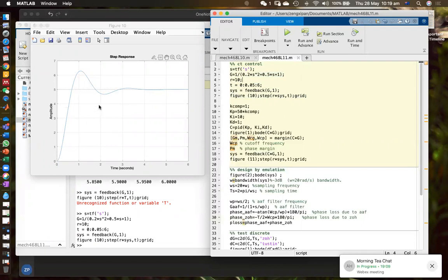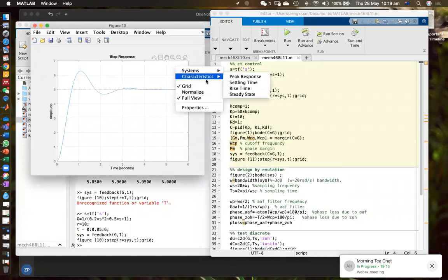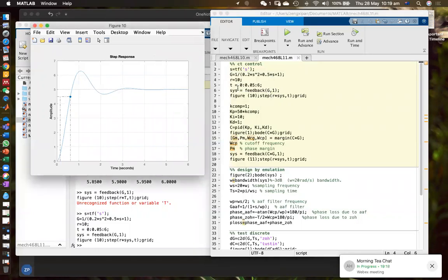It takes like 2 or 3 seconds before it becomes stable. Rise time is 0.5 seconds ish to get 90%. Its overshoot is more than 20%. Okay, so the main problem is it's not getting to our reference. So it doesn't go to 10.